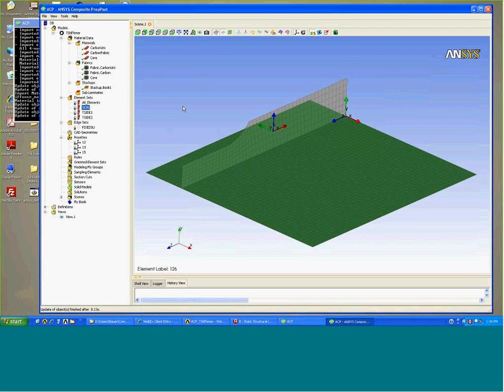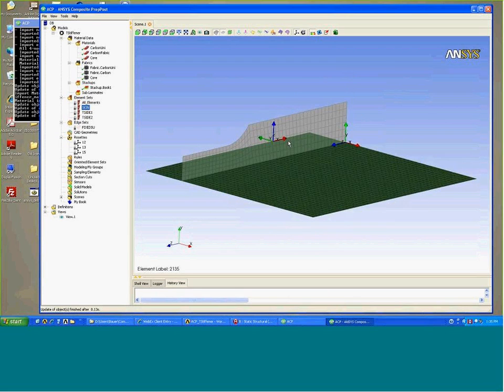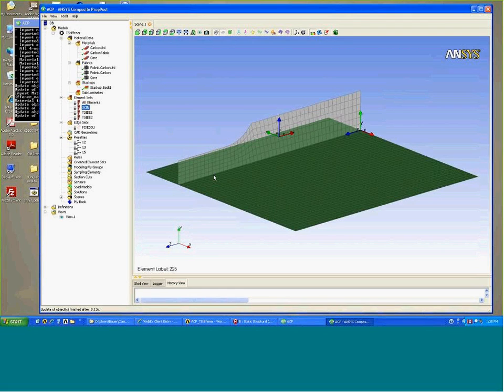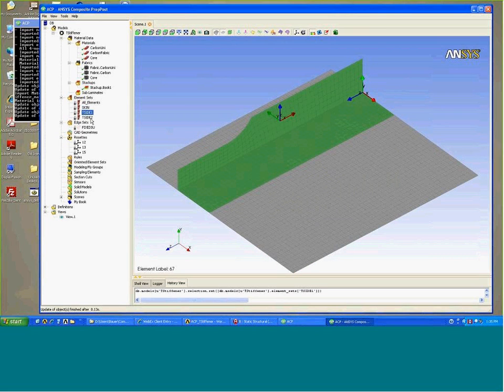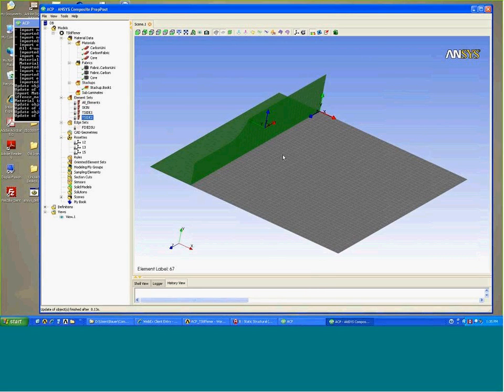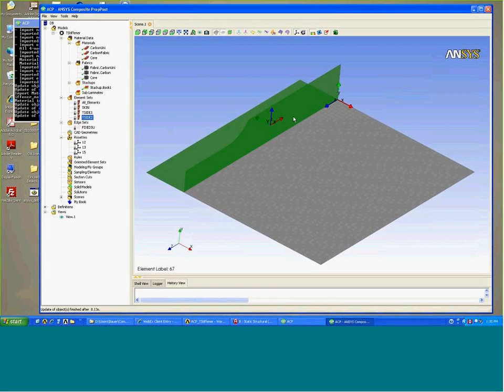You can see the lock symbol here. These are imported with the CDB file or from Mechanical, and you cannot change these. If you want particular groups of elements, you can create additional element sets. I created named selections with the geometry in Mechanical, and this makes the ply definition and assignment pretty easy. We can see these are pre-built for the skin, which covers the entire section, and the two sides of this T, useful for defining the two L sections.